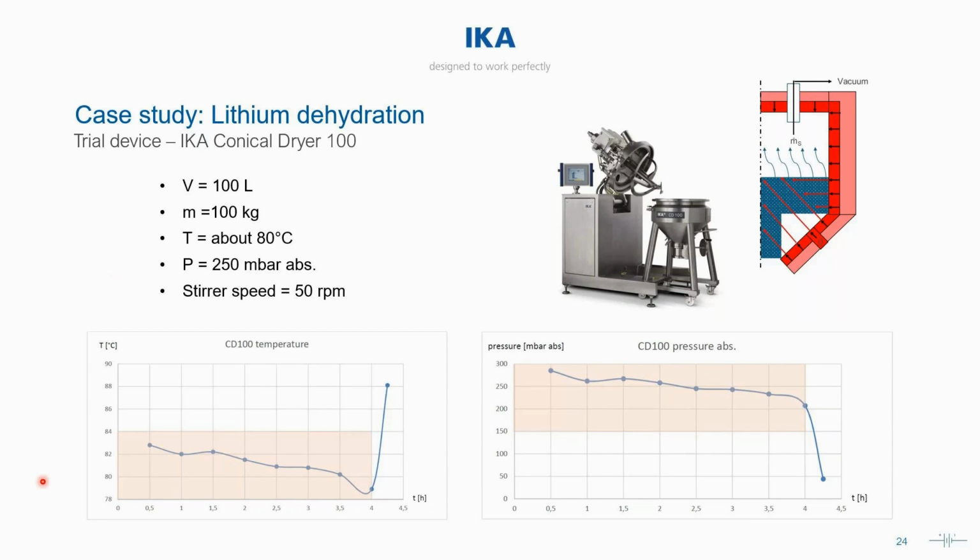So as we see on the graph on the left, when we first started out, even though we were imparting heat energy, the temperature of our material was not rising until we got to about hour 4. And we know why this is. This is because the heat that we are imparting is going towards evaporating the water instead of the specific heat of the material. So we look at this data and we assume that right around hour 4 is when most of our water has evaporated because we are actually seeing a temperature increase in the bulk material at that point.